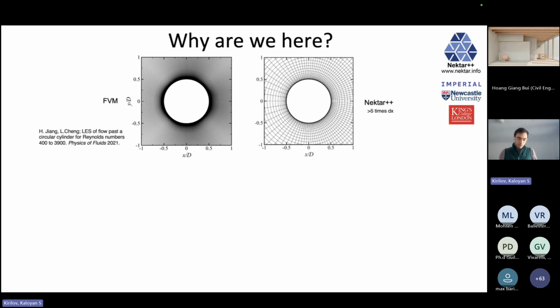It was mentioned earlier that high-order methods are agreed to be very accurate and to have very low dissipation. But if you use a high-order method with a linear coarse mesh, you might actually end up with a very oscillatory solution. This is, for example, a flow around a NACA 0012, with a very coarse mesh. What you can see is that if you use a geometry of polynomial order 1, like a finite volume mesh, you get very oscillatory behavior.